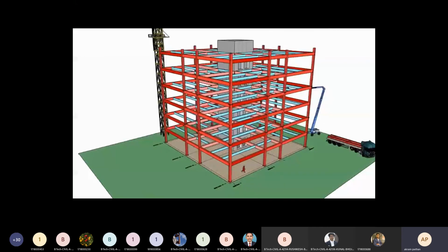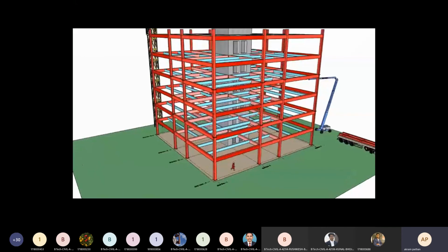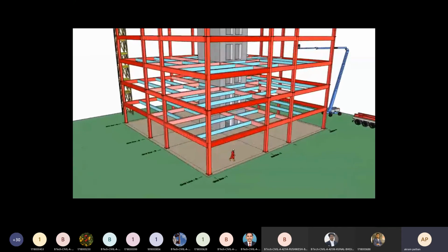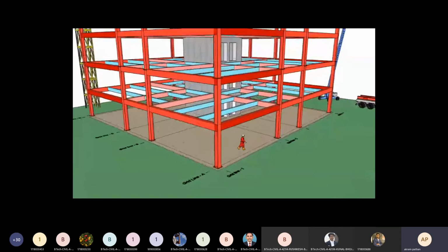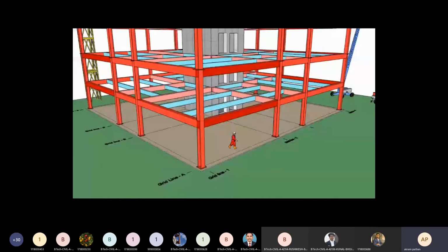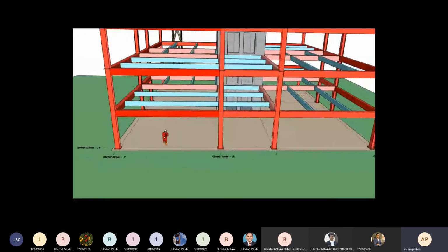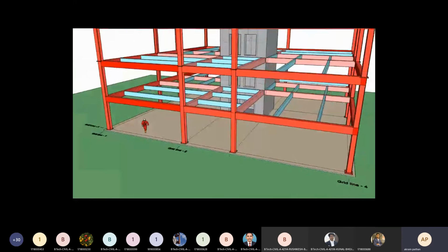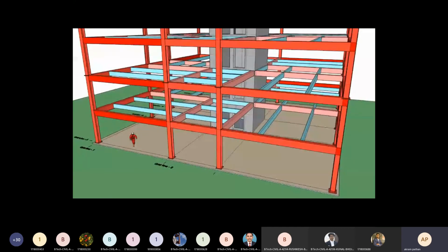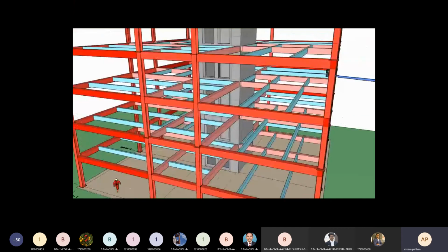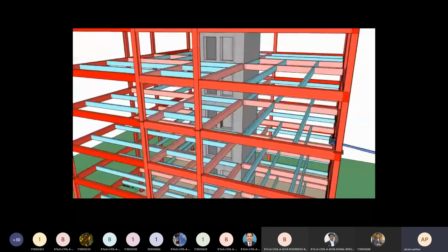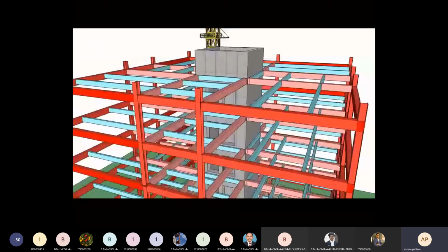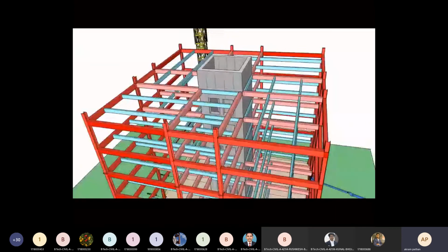Crane lifting operation. To lift columns, connect lifting hooks to design lifting points or brackets. To lift beams, two-legged slings will be used and will be double wrapped to prevent the legs sliding together. Lifting hooks to have safety catch. Tag lines will be attached to the load to prevent the load spinning and swinging and to help to position it.